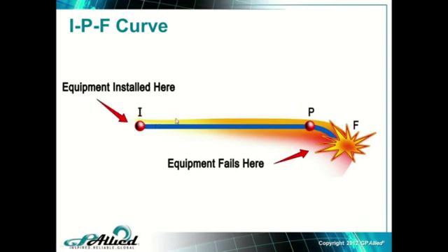So the whole idea of understanding bearing failure mechanisms is to, one, get a very good feel for how our condition monitoring technologies are working and what it is they're actually looking for. And then two, take that information and translate it into different actions on a daily basis with our craftspeople, with our operators, with our engineers and technicians, and create a situation where we're extending I further back, extending that I to P interval as long as we possibly can.